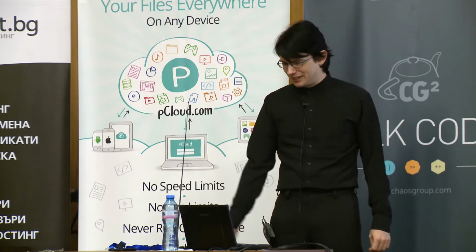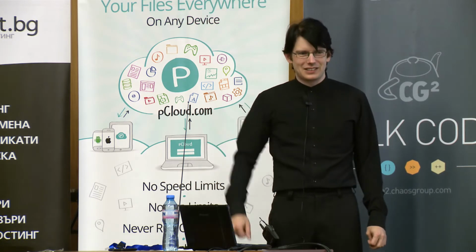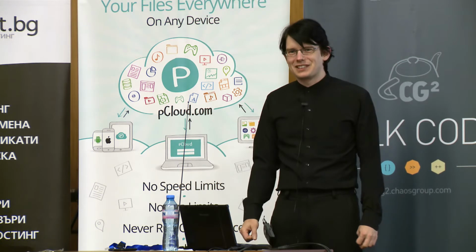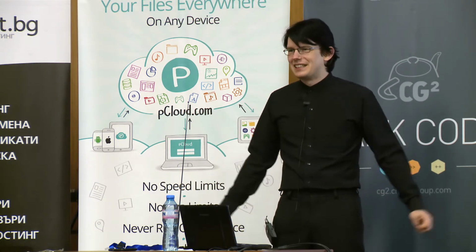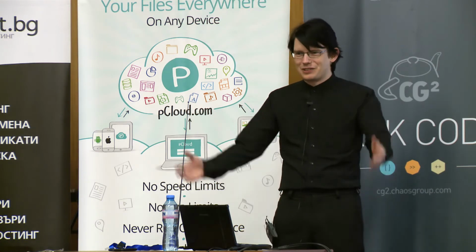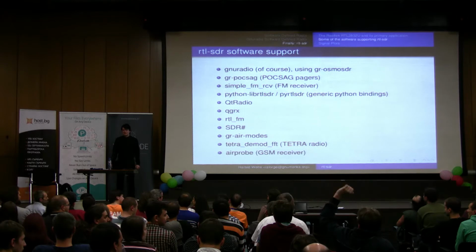We can of course try some other things. I can quickly see if I can find an online decoder for the ADS-B, so we can copy and paste those hex strings and see if we get some more information about that. But otherwise, I'm happy for suggestions on what we should try, or what you want to know about rtl-sdr.